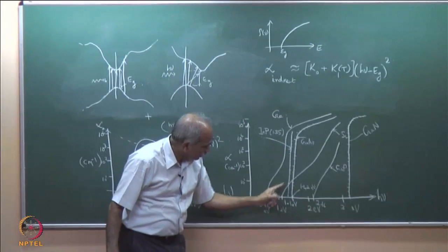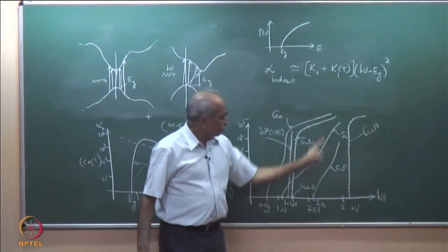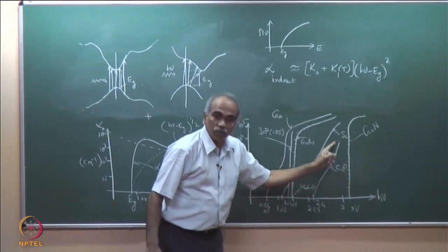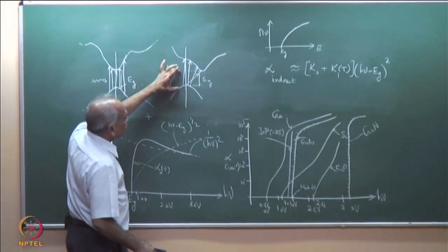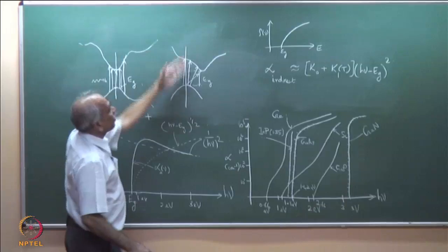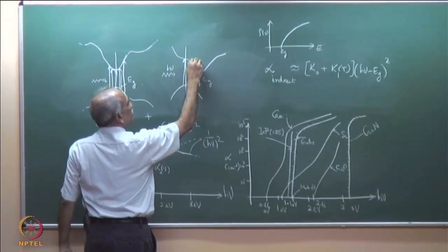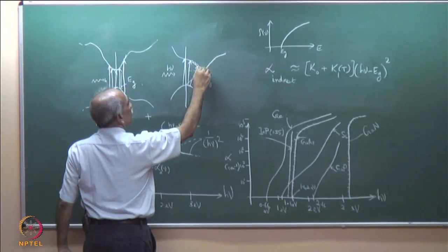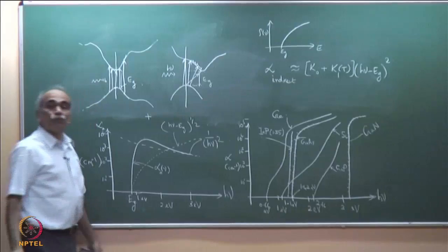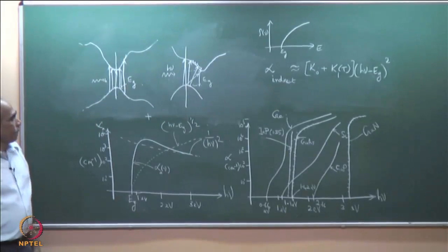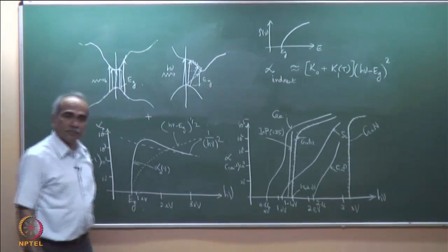Same here with silicon. You see, it was going like this, then again it started increasing. Same here with gallium phosphide. So, as the energy increases, the probability of vertical transitions increases, and once of course the carrier comes here, then it will thermalize and come down here like this. This is thermalization, which we have discussed, due to phonon transitions, and therefore, the graph again shoots up.